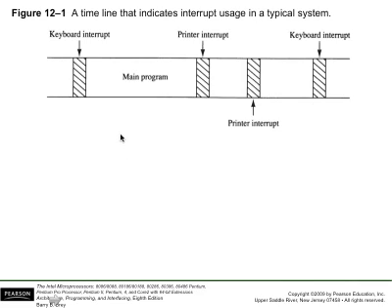During this shadow phase, the processor will know there is a hardware interrupt. It will stop the software execution of the main program and then switch to the execution of a special program we call the interrupt service routine, specifically for that particular hardware interrupt signal.